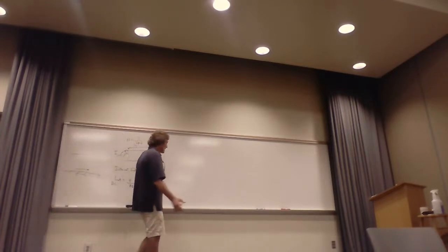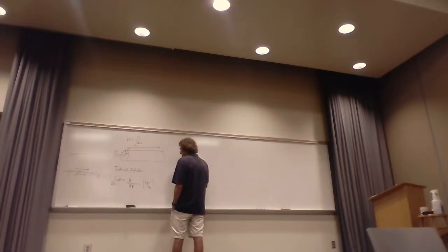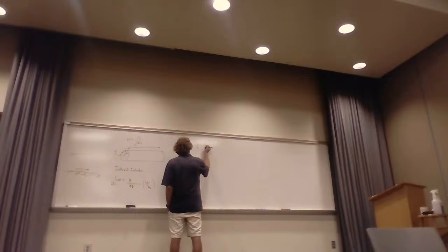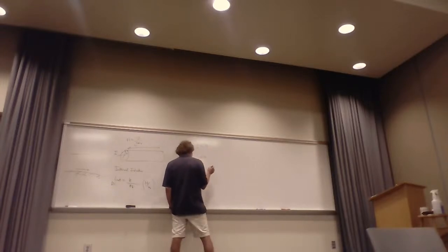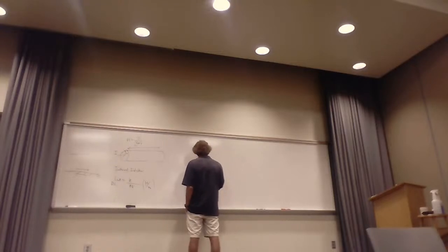Now when all of a sudden the skin depth is going to be less than the radius a of the wire, then you get the internal inductance. This is still internal inductance, but now it's AC, or high frequency. This is still going to be mu 0 over 8 pi, but then it's going to be 2 times the skin depth over a.